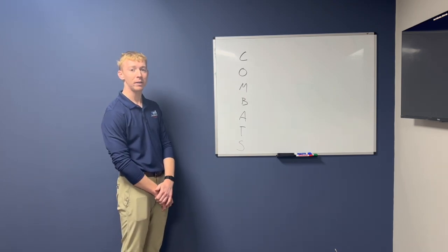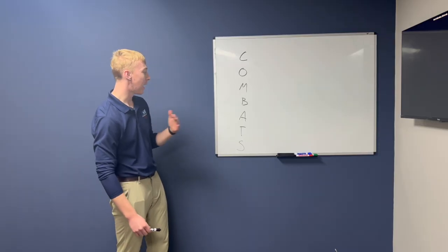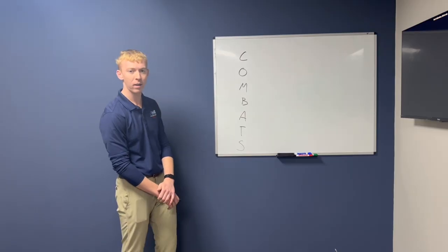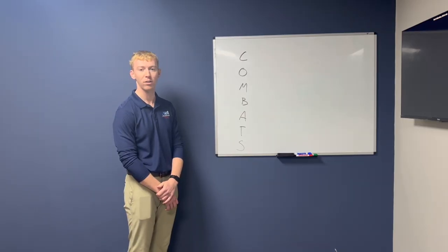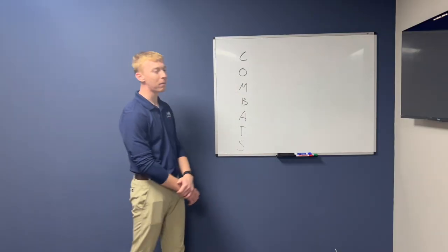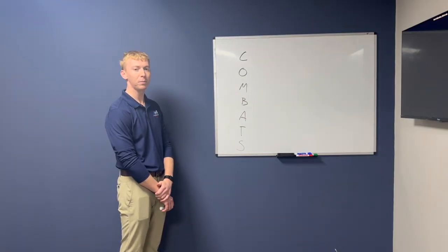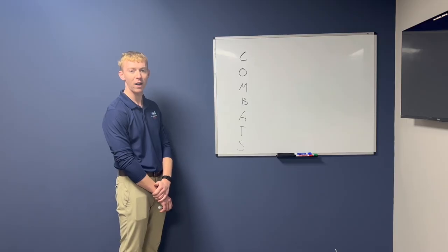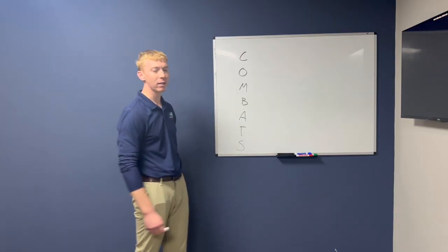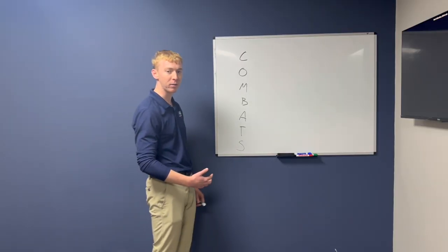In addition, it'll be tested with an aft center of gravity and a takeoff configuration with the flaps and the gear up. Finally, it's tested for a standard day. Now, this is what the manufacturer must comply with when making the VMC. The VMC speed for our aircraft is 65 knots, but that is a fluid airspeed and it will change. We're going to discuss now why VMC speed changes.